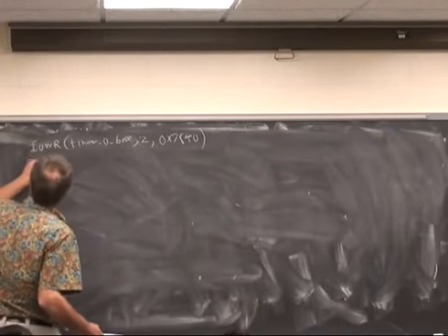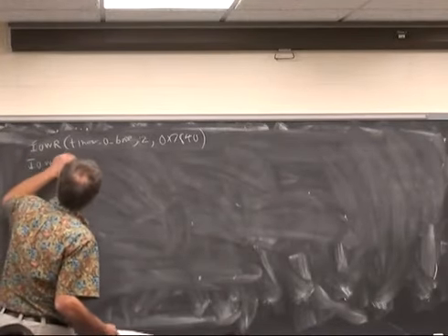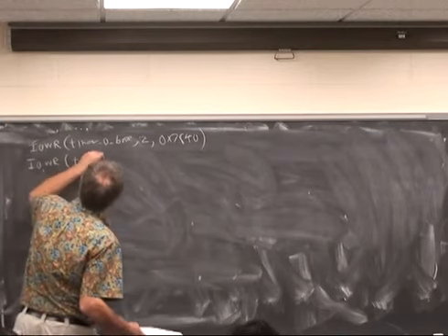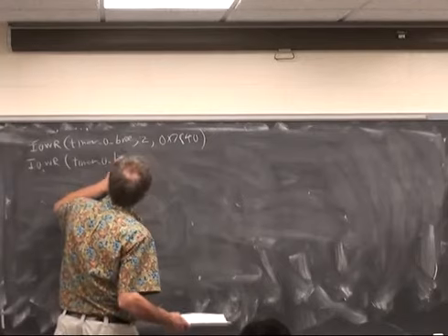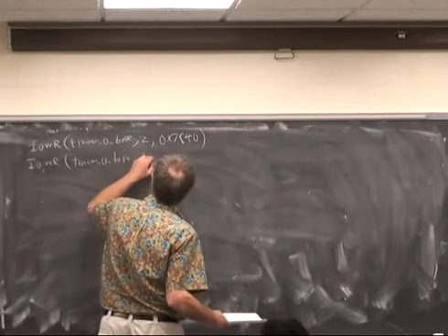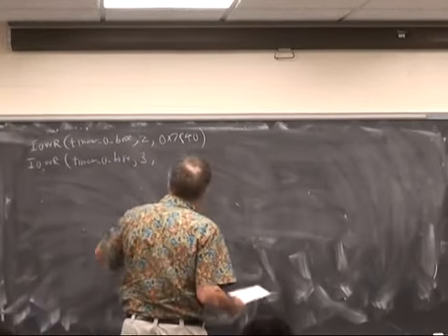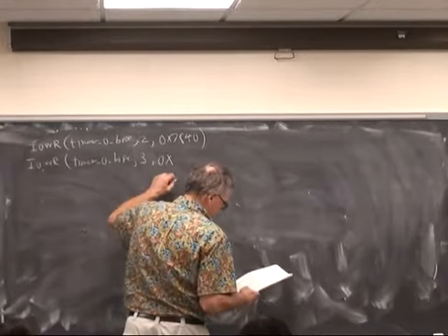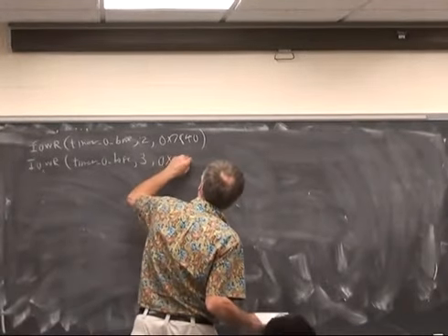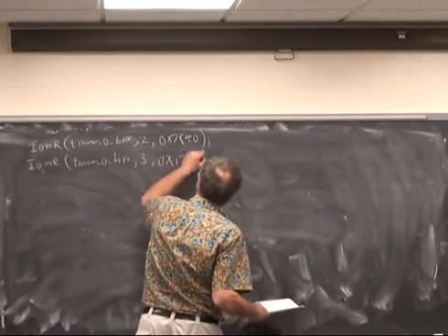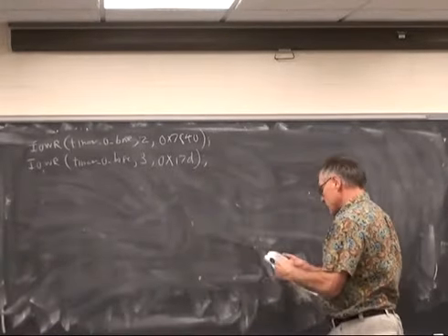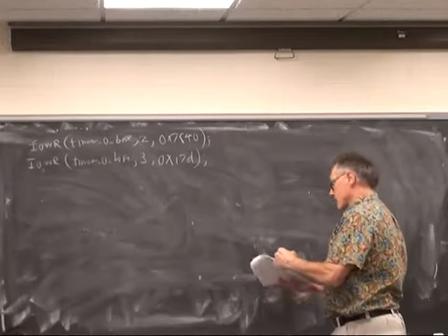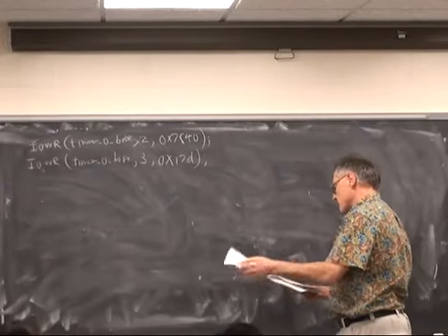And we're going to do an IO write timer 0 base, 3, 0x17D. That sets the timer to 1 second. Half second, excuse me, half second.